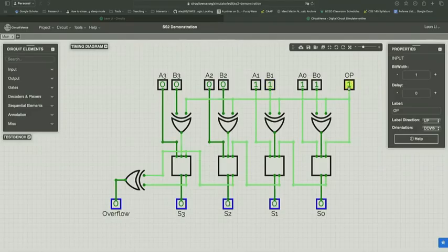When OP equals 1, it does two things to my adder circuit. Number one, it sends a carry in of 1 to the first adder bit. Secondly, the 1 controlling the XOR gates makes them work as inverters. So now you're inverting your B inputs, flipping each individual bit of B, and then adding an extra 1 from the initial carry in. So now this should work as a subtractor. Again, right now my input is 0011 minus 0011, I get a 0. If it's 3 minus 2, I get a 1.